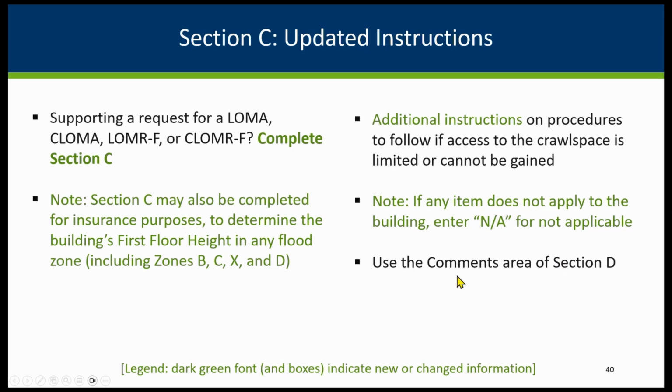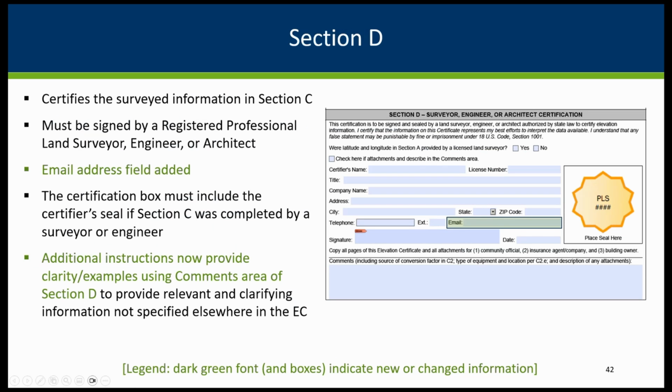And there's many places where you need to put comments in section D. So it's pretty rare that you don't have comments in section D. And speaking of section D, that is where we basically should have the surveyor, that licensed surveyor or the professional engineer who's qualified in this area, signing, and when it's applicable, putting the seal. Not all states require the seal, so put whatever's required in your state where you're completing that elevation certificate.